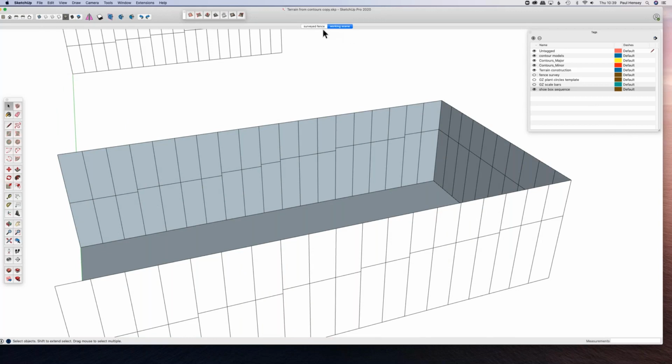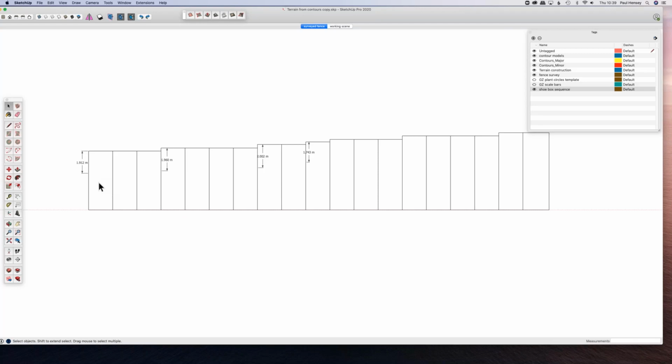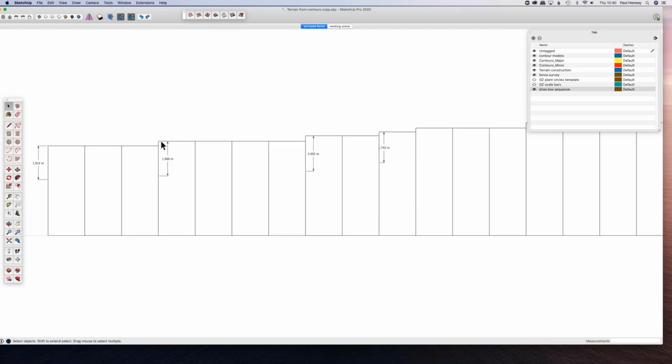To give you an example, your drawing might look something like this, that you've drawn in every 2 meters on your little survey drawing, and you've then said, right, the first fence panel is 1.92 meters from the top of the panel to the ground. And then you might do it every single panel, or you might take one wherever there's a change of level, because you need to check that the fence panels are level. So maybe having a spirit level helps.